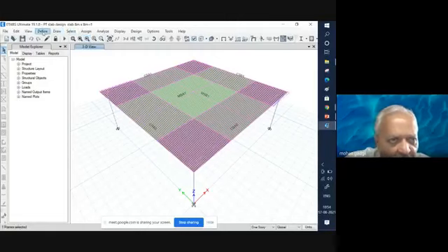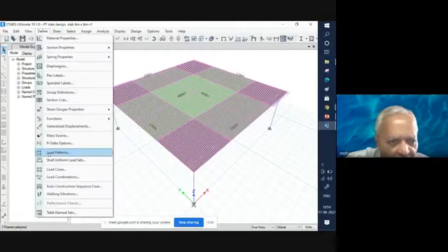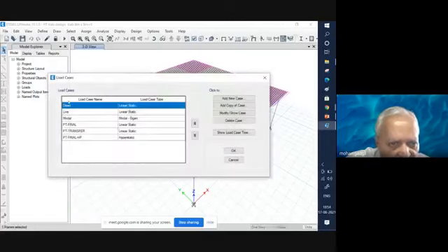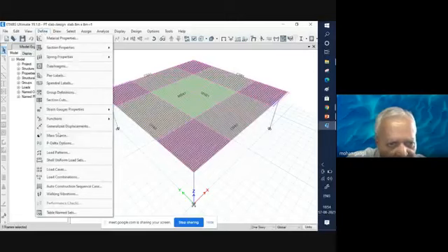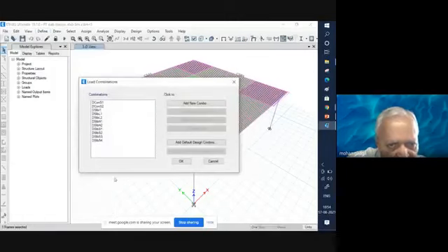As far as the loading cases are concerned, we have again on the same lines the dead load, the live load, then we have PT final, PT transfer, and PT final with hyperstatic stresses calculated. And we have the load combinations on the same line. So we have all these default load combinations which are internally developed by ETABS itself.